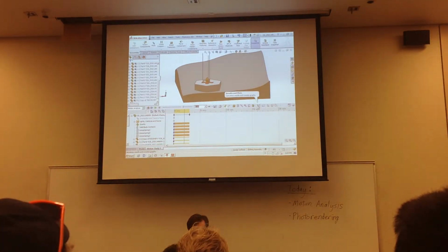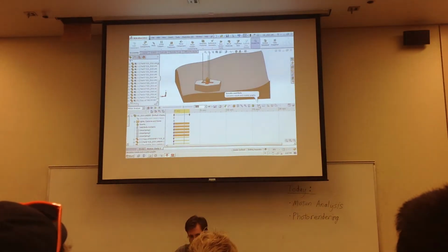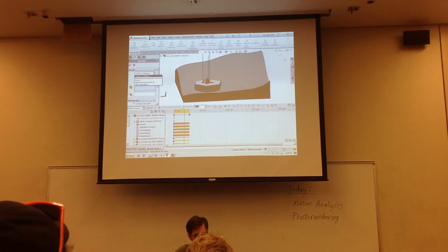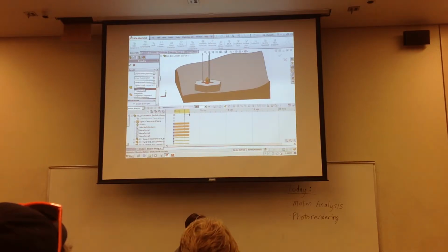The other result is to actually plot the acceleration as a function of time. So we go to the same results plots button, choose a category, it's still the displacement, velocity, and acceleration. A subcategory, we can do velocities or displacements or accelerations, and we can do linear or angular. We're going to do the linear acceleration, and then we'll select a result component, so you could do it in the X, Y, or Z direction, or we can do the overall magnitude.